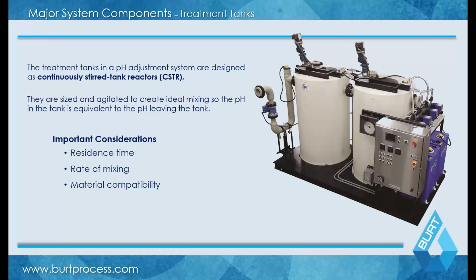The rate of mixing, obviously, we'll talk about in a moment. And then there's material compatibility. You are dealing with acidic or basic chemicals. The majority of pH neutralization tanks are going to be thermoplastic. They're going to be stainless steel. They're going to be some kind of corrosion-resistant material, possibly fiberglass if you have a high-temperature application in those cases.